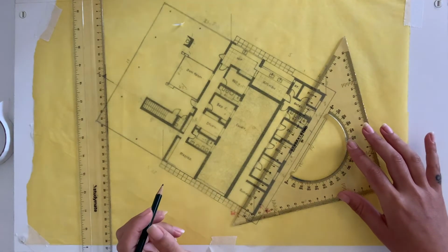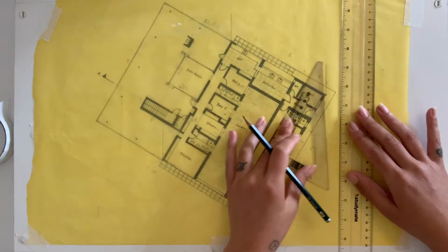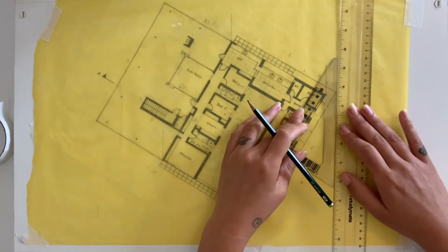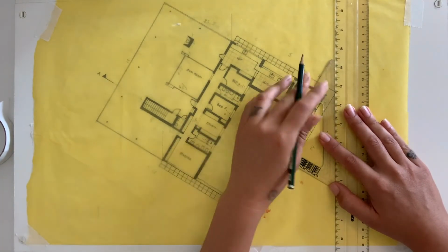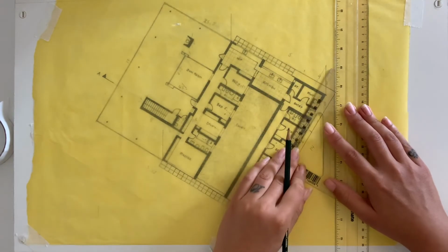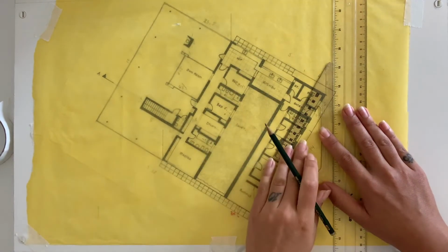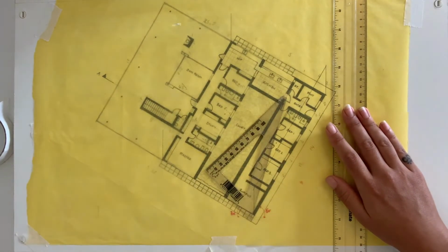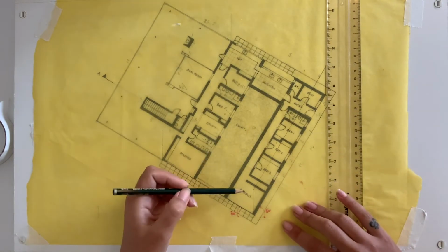Or if you want to be precise, then I suggest you go with the T-square. So you'll lean your 60 angled ruler onto the T-square, and then make sure that this angle will meet the other vertical line at the top of the wall below. This gives us a precise angle if it's the 30 or 60 degree or 45, whatever we need for the drawing. We need to reference from this angle that we've drawn if it's locked in with the T-square.